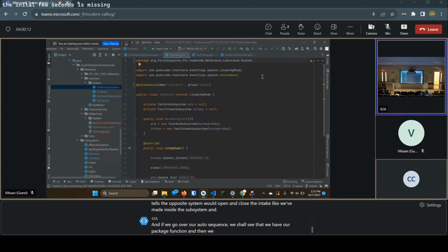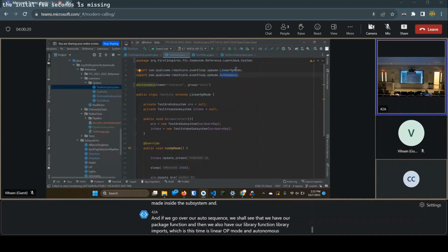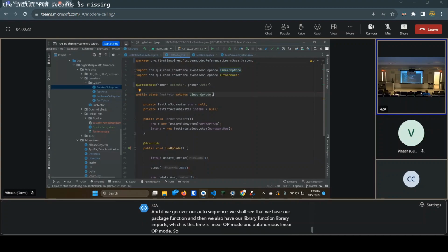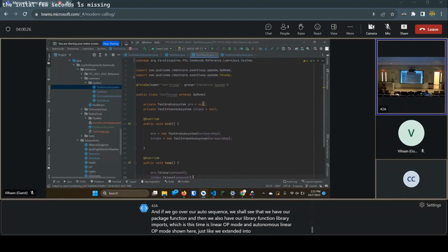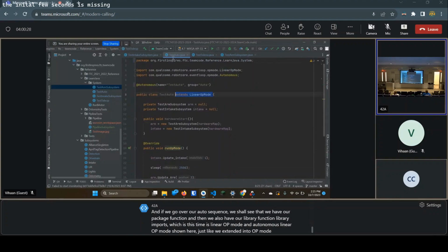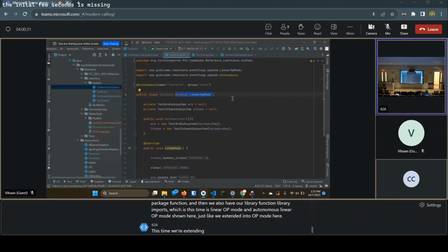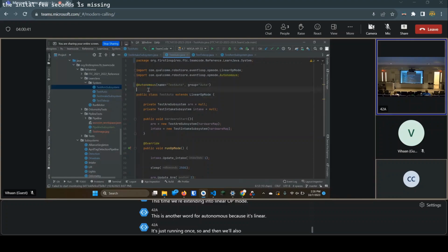This is important, because if we just quickly drive up and then quickly place our game element, we might still be moving. When we say motor.setPower 0, it sets the power to 0, but it doesn't press the brakes on the motor, it just turns off the power, so it's drifting a little.